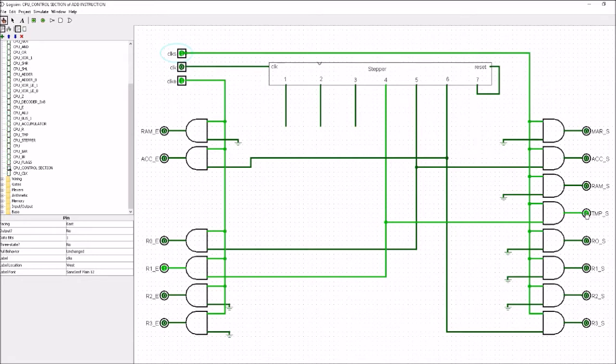So it means that we've now taken the information that's on the bus and we've written it into the temp register. And of course the clock set will go low again, and that's it held within that temp register, and then the enable will go low again, and we're in a position to continue on with the next step.